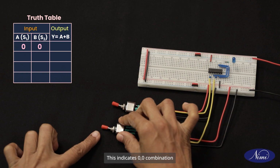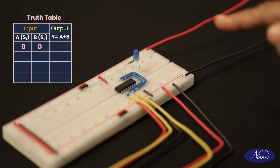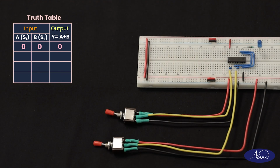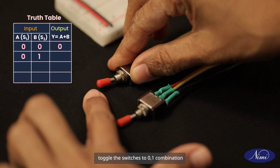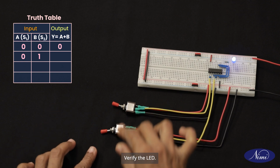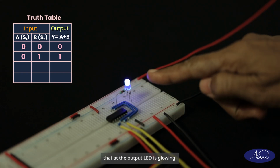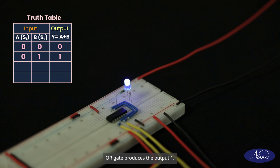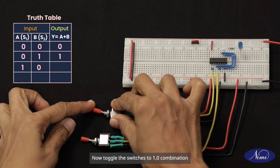This indicates 0-0 combination. For this, let us verify the LED. It is not glowing. Now, toggle the switches to 0-1 combination. Verify the LED. You may observe now the output LED is glowing. So, we know that if any of the input is 1 or both are 1, OR gate produces the output 1. Now, toggle the switches to 1-0 combination.